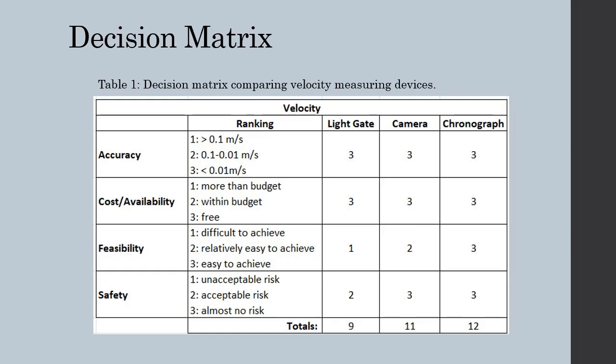This study relates muzzle velocity to distance. Two alternatives considered for measuring velocity were a light gate or high-speed camera in conjunction with precise measurement marks. Though a light gate's resolution is higher than the chronograph, around 5 microseconds compared to 0.13 milliseconds, the resolution difference would not affect the results enough to outweigh the convenience of using the chronograph.